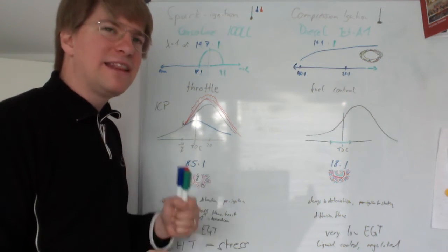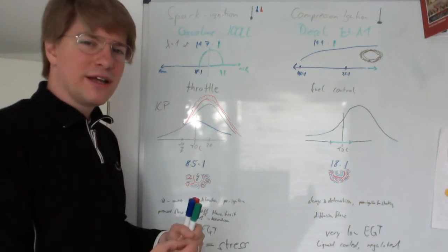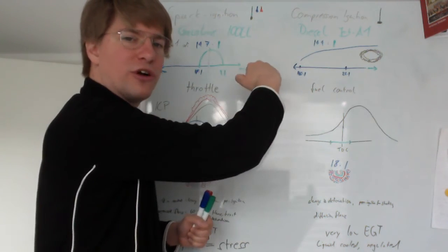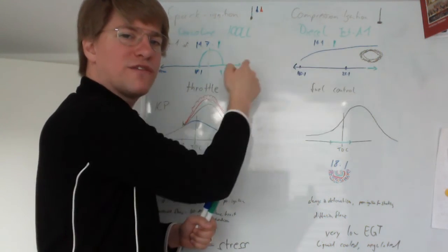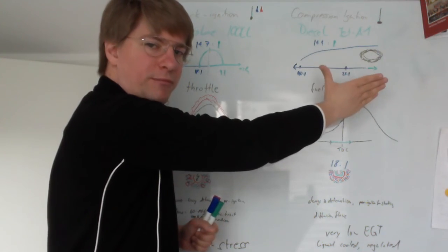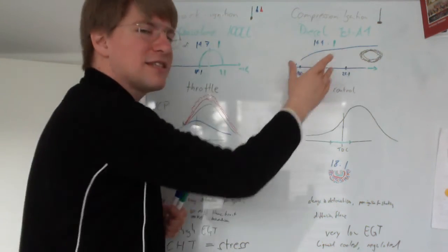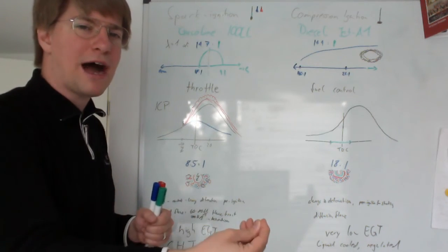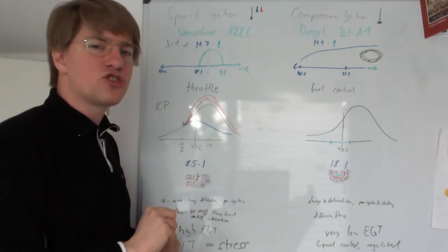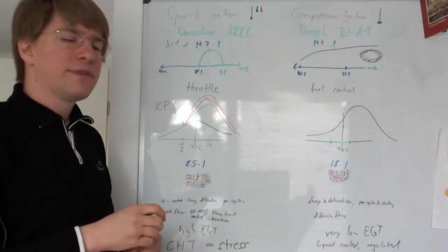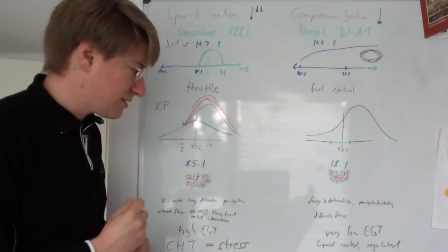Imagine that. And the only reason it works is that the mixture curve is so much longer and so much flatter for burning diesel fuel than it is for burning gasoline. And that is the only reason why controlling the power by means of mixture only works.